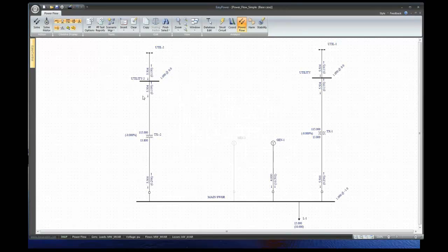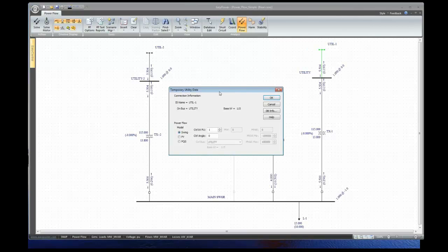But what about the power flow? I have two swing sources. How do we determine how the power requirements get split between the two sources if everything else is equal? Well, we have what we call the control angle, and this is the phase angle between the two voltage sources. I call it the power angle maybe.